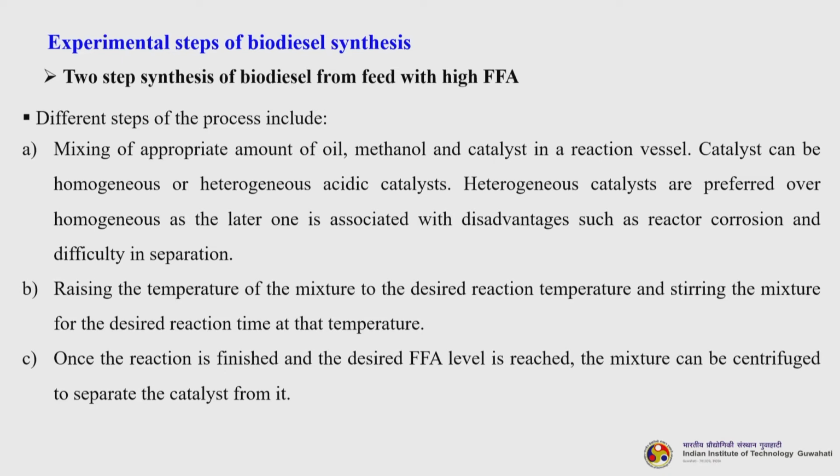Heterogeneous catalysts are preferred over homogeneous, as the latter one is associated with disadvantages such as reactor corrosion and difficulty in separation. Now, second, raising the temperature of the reaction mixture to the desired reaction temperature and stirring the mixture for the desired reaction time at that temperature.